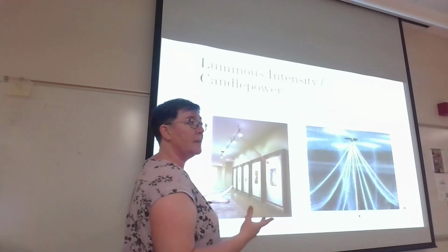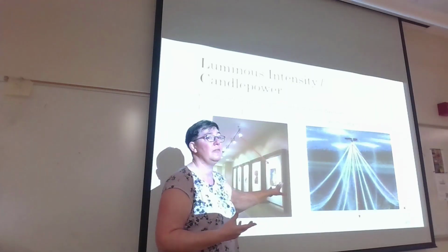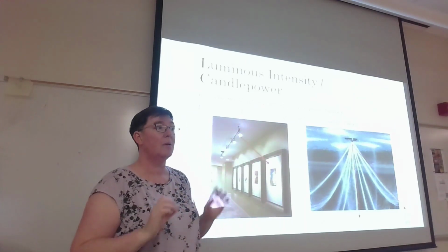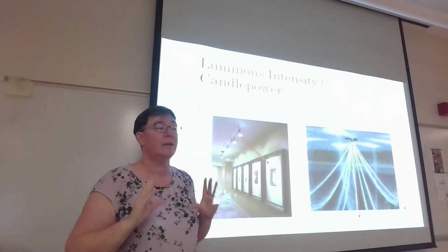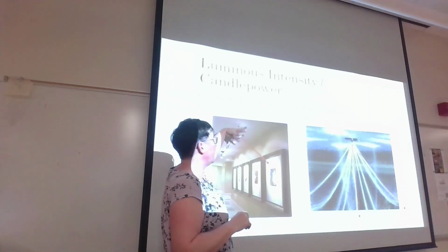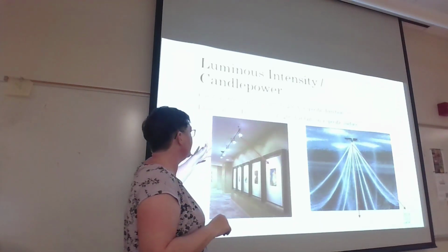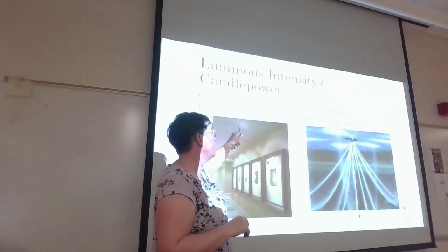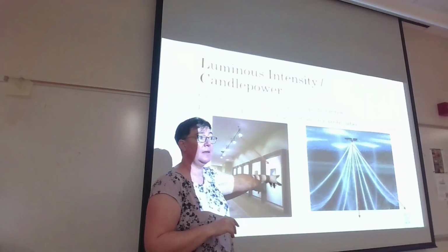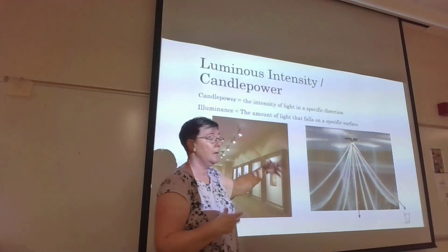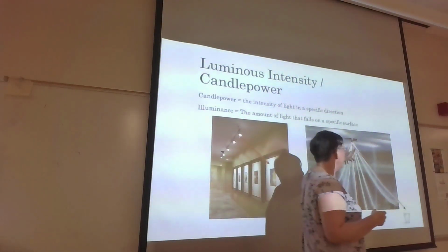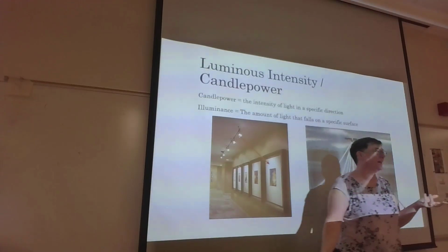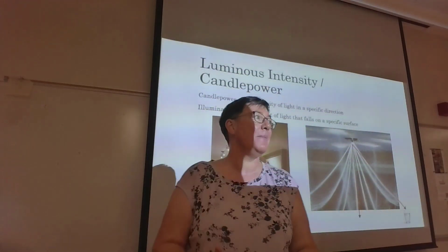So why are we talking about this? It's because we've switched from talking about ambient lighting to now we're talking about task lighting, where we're interested in a very specific surface. So this light fixture is like a water fountain spraying out lumens, and we're interested in not the total amount of lumens. We're interested in the ones in this direction that hit this task. That's what we care about. So back to our water analogy, we're interested in what ends up in this glass. Right? Not all of the rest of the lumens, not all the rest of the water coming from our water fountain.